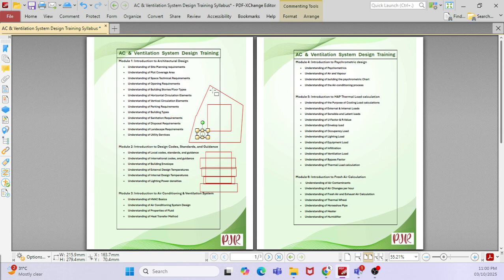Maybe I will give you some assignment to read architectural guidelines so that you will have a basic idea. Sometimes they will say 2.4 meter height, sometimes 3 meter height. Sometimes if you see the project, the floor height will be 5 meter, sometimes 6 meter, sometimes 4.5 meter. Double height areas, how to decide, that is based on the architectural guideline. So you will have that understanding first.